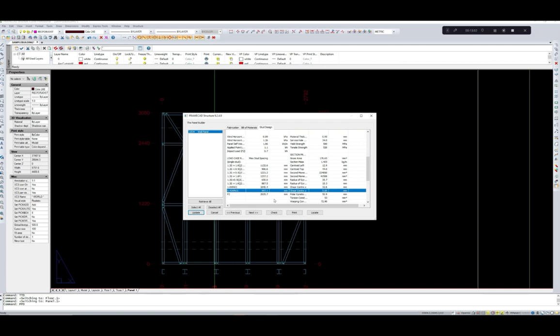So, even in an experiment performed by a reputed institute, we have found that the lateral deflection of the strut due to wind pressure is about 70% because of the presence of the sheathing, that is in the form of boards, cement boards.